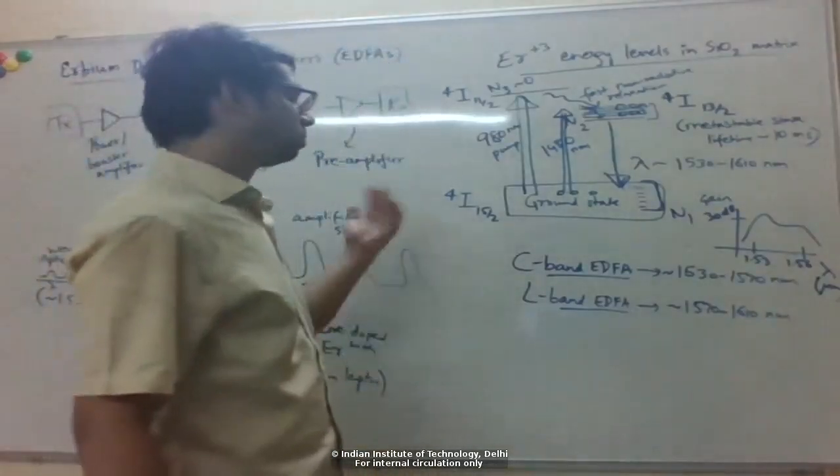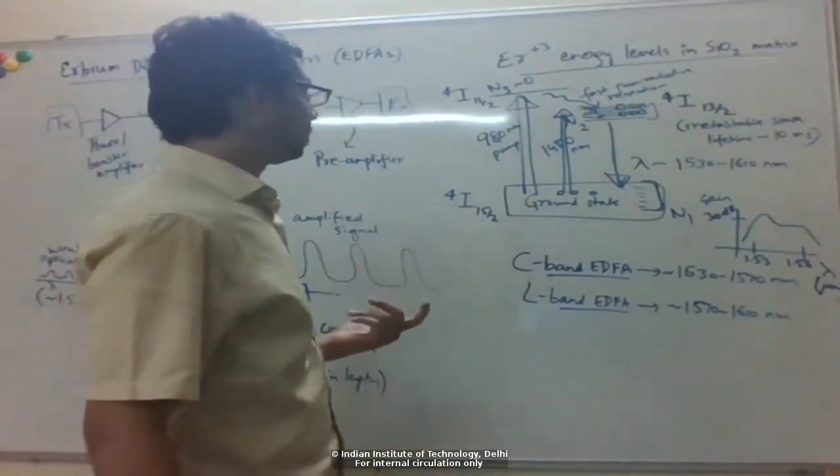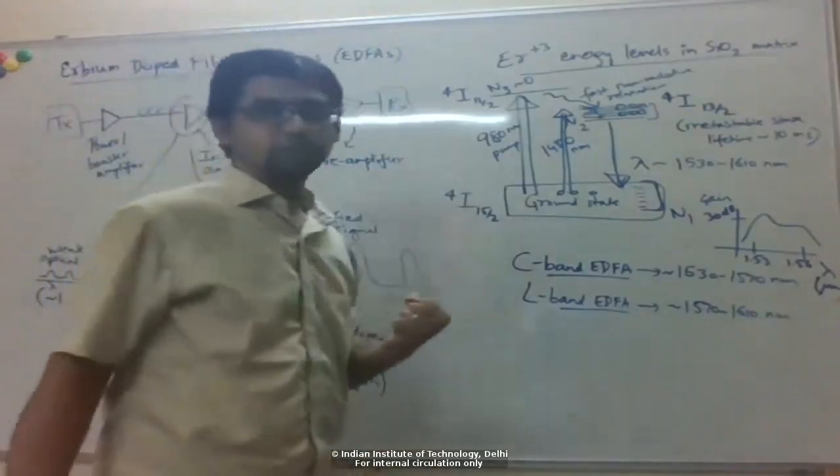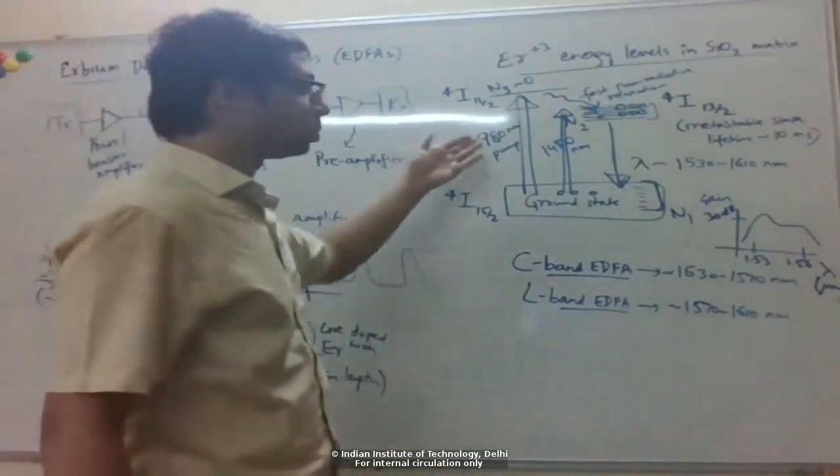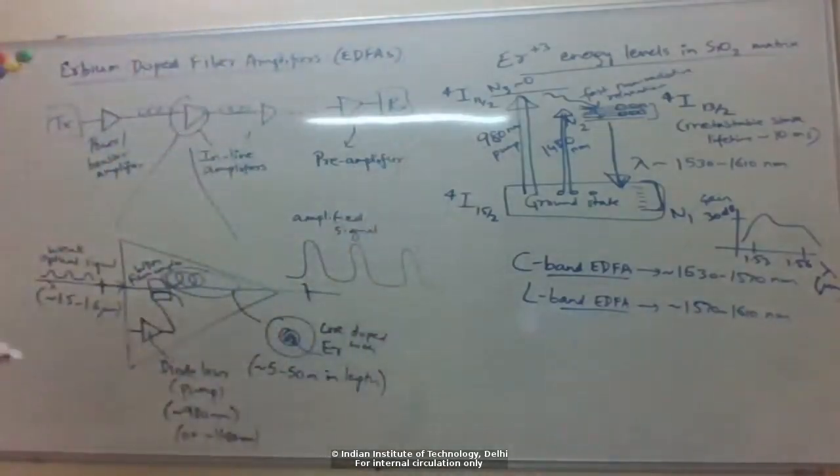But the performance that you get with a 980 pump is usually much better. So most EDFAs use 980, mostly in terms of the noise performance.